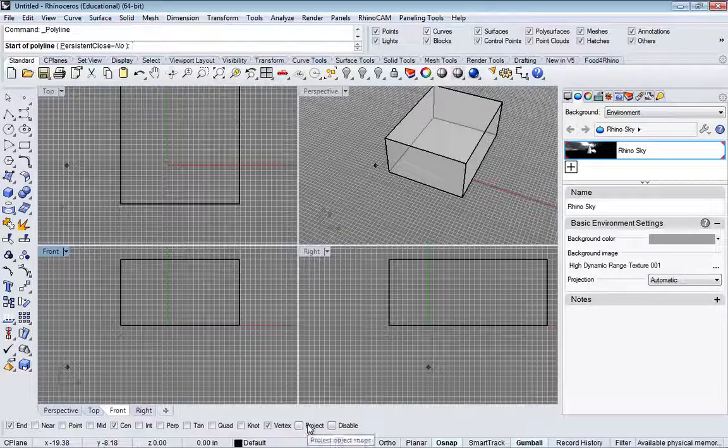And then there's also this idea here of projection. And so remember how I talked about construction planes? So when we're working in 3D space, sometimes when you're drawing in perspective, it doesn't know exactly, it's going to guess which plane that you're on. And you can use projection to make sure that it's always being drawn on that construction plane. So that can be helpful. You can quickly turn off these things. And then below that, here we have what C-plane you're working on, the coordinate systems down below, and the scale that you're working in.